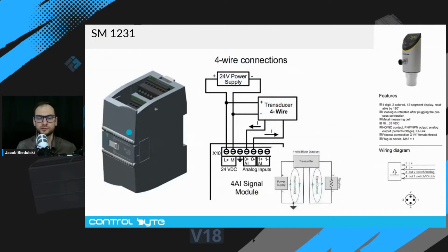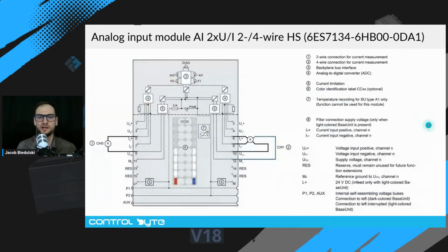For the S7-1200 modules, to power the sensors, we had to use the same power supply as the power supply for the module. So we took the potential from the SMPS that is powering the whole module, okay? The ET200SP system has more connections, and here you can see the terminal blocks for these systems.